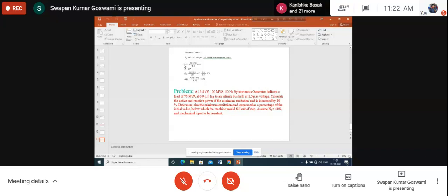That means strong coupling between the active power and delta, weak coupling between reactive power and delta, strong coupling between excitation voltage, that means the field current, and reactive power, and weak coupling or no coupling between field current and active power. So this is established, and this was the purpose of discussing this problem here.